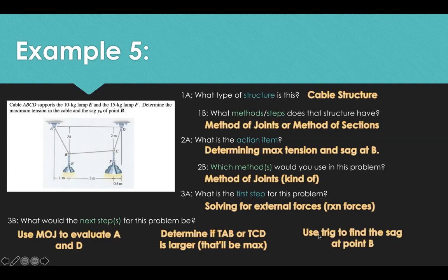Exactly. So you know that the slope of your reaction force resultant has to be the same slope as this cable. Going back to what I said earlier in the cable slide, your reaction force has to be parallel to the cable anyway, because it's just opposing the pull on the wall. So you know the slopes are the same, and the slope would be rise over run.